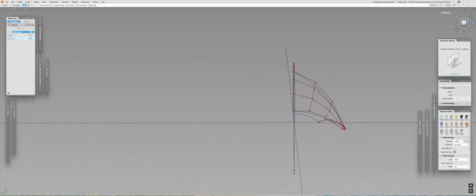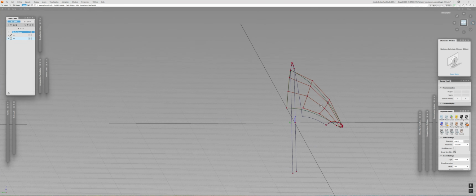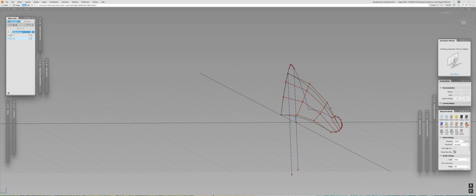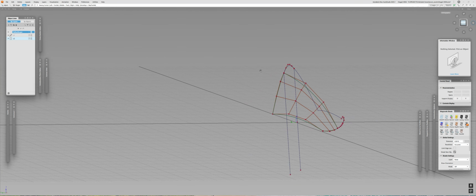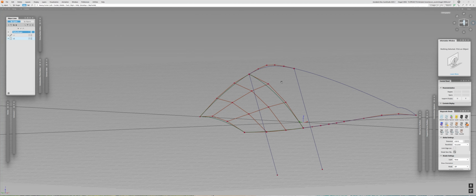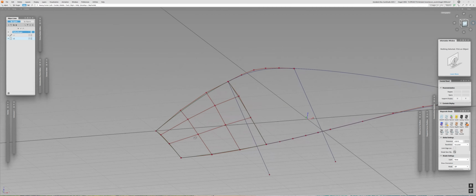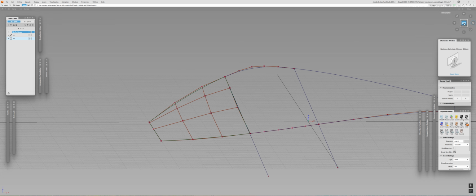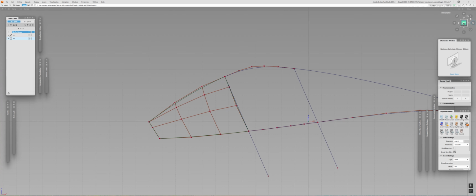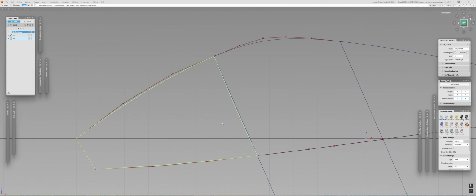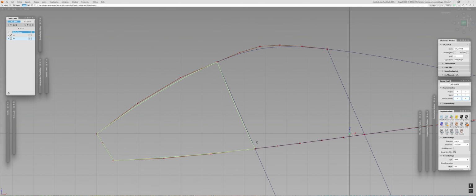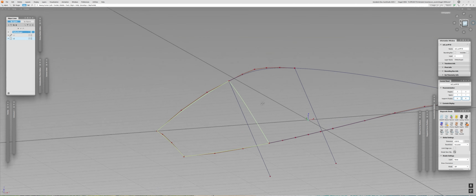On top of that, I don't believe that this arc is natural for what we have, but if there is tangency, the lines will follow completely differently. So this edge can't be treated as a proper edge. On top of that, if I look closer, you will notice that the line itself is not straight. So it bends, and I would like to have a straight edge. So we need to fix this also.